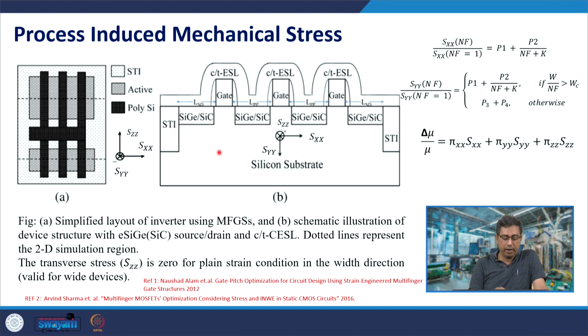on what is needed. Likewise, for PMOSFETs, instead of using silicon source and drain, you would etch out the silicon and deposit silicon germanium in general. So that would increase the compressive stress of the channel in the x direction. Compressive stress of the channel would increase the hole mobility. Because the STI is deposited at a high temperature and then cools down, that again applies a compressive